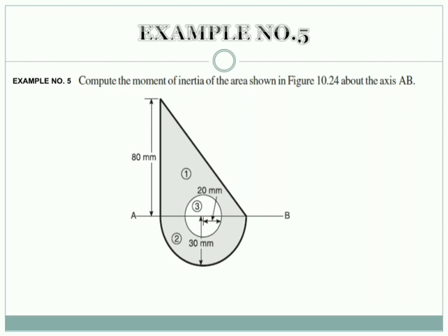Carefully if you see, the diameter of the semicircle is available, which is 30 units or 30 mm. Hence the base of the triangle, the radius is available, that is 30 mm. Hence the base of the triangle is twice the radius, therefore it will be 60 mm. So base of the semicircle and base of the triangle here are the same.